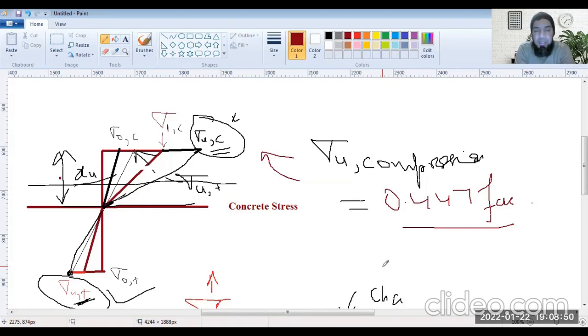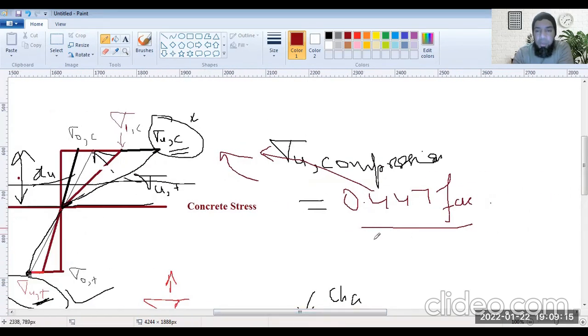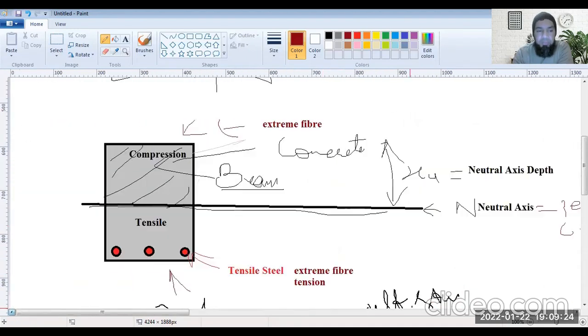In flexure, जब ये flexure में होगा, its failure is still happening in tension first. तो लेकिन हम इसको डिजाइन कर रहे हैं for compression only. तो tension के लिए क्या कर रहे हैं? This is the compression failure, लेकिन इसका failure तो पहले tension में हो चुका होगा. So इसकी तो नौबत ही नहीं आएगी कि ये कंप्रेशन में फेल हो जाए. ये तो पहले ही टेंशन में फेल हो जाएगा. So what do we do? Which we assumed first, that we will provide the steel bars at the bottom of this beam or this flexural member.